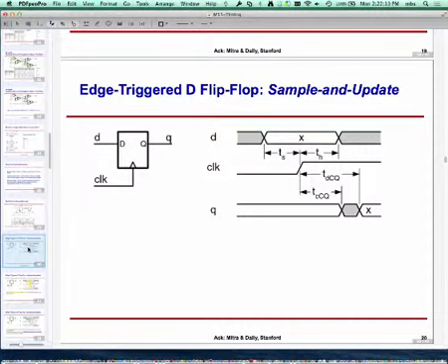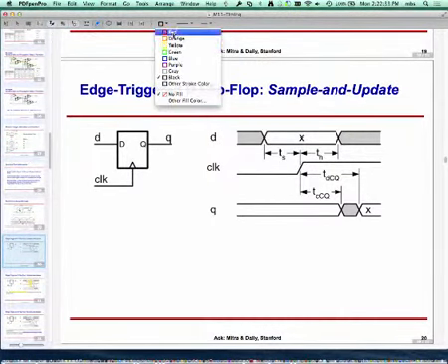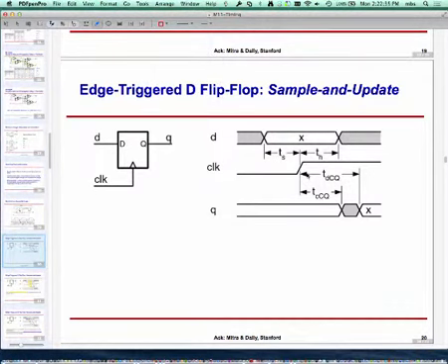basically have two timing attributes which are of considerable importance, because ultimately they are making a decision at a point in time. One is called the setup time, which you see out here. The setup time means that for the flip-flop to work correctly, the data must be stable for some time before the clock edge.